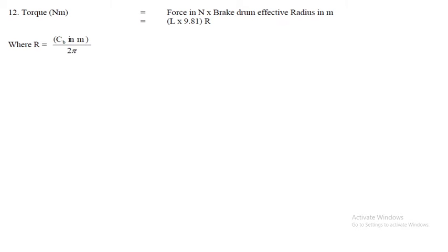Then we have to calculate what is the torque. Torque produced by the engine is the force in terms of Newton times the brake drum effective radius in meter. Here the load is in kg; load in kg multiplied by 9.81 will give us Newton.